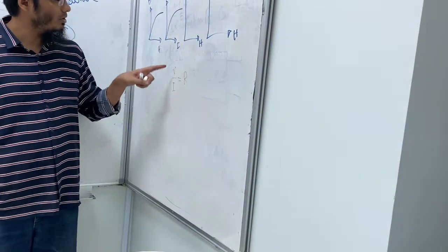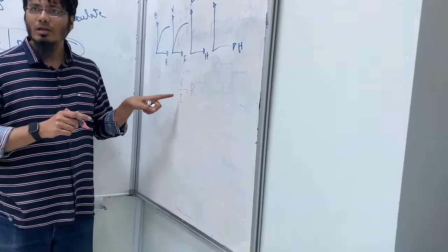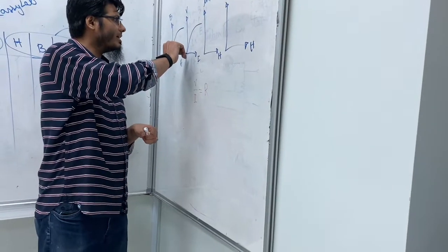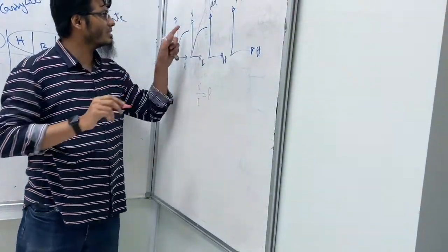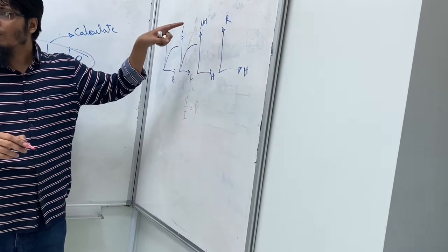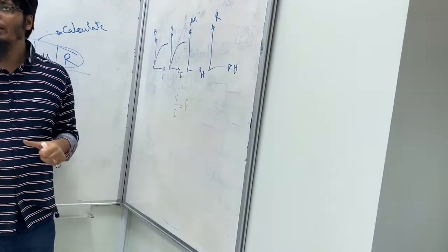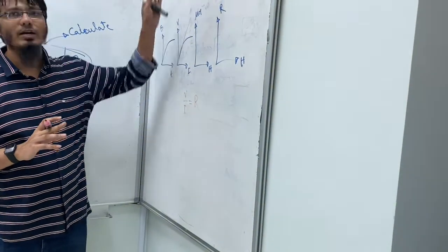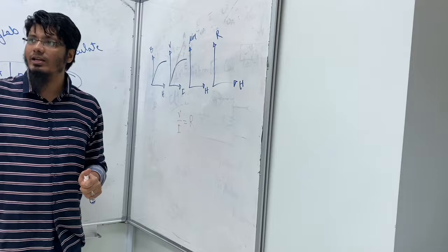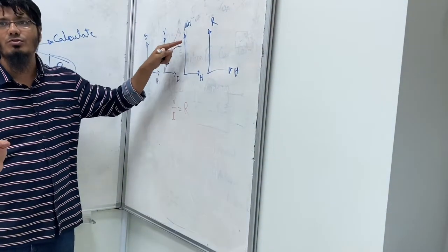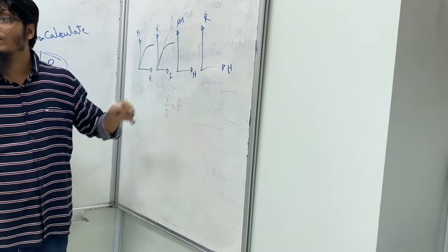So if you plot the curve, you will always get a straight line, isn't it? Yes. So Ohm's law says that the voltage versus current curve should be a straight line. But whenever you apply this in the magnetic circuit, it doesn't look like this. It cannot follow the linear curve. Rather, it follows the linear curve for some time and then it goes to saturation. So this is a special case.